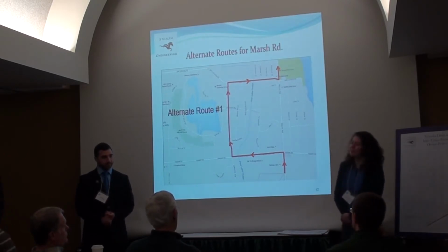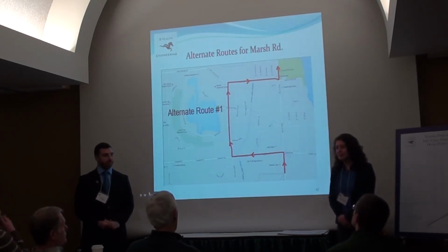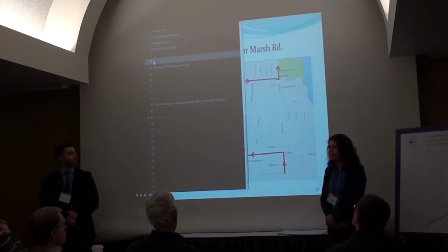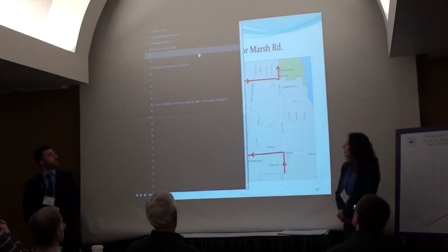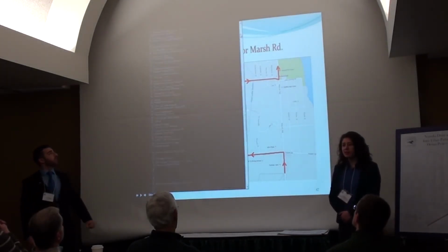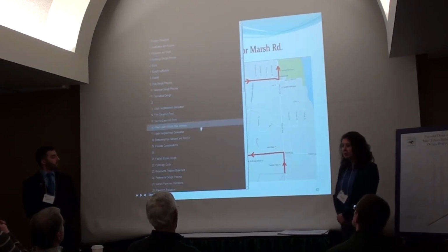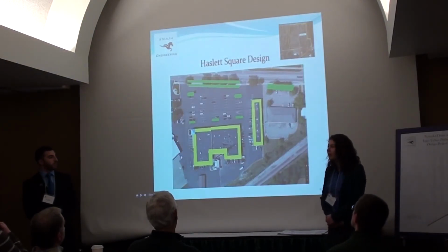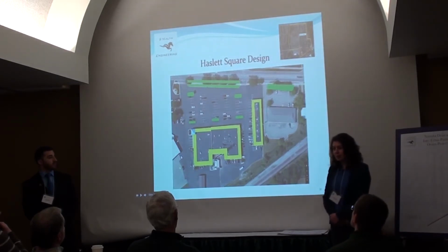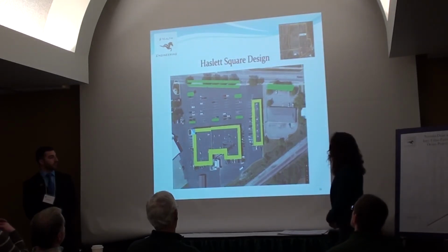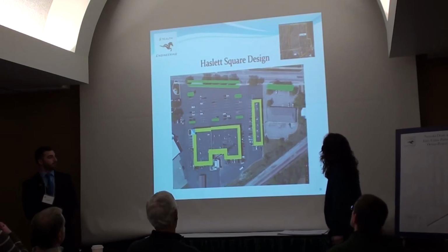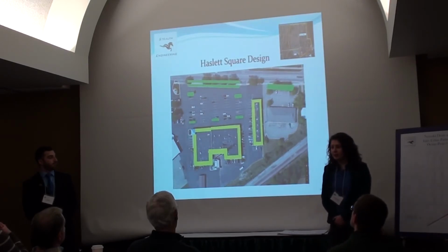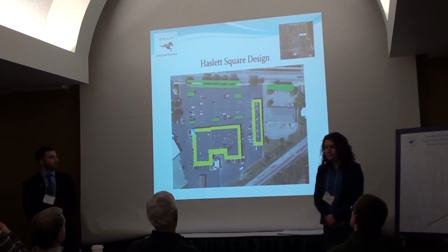Yep. I found the drainage area to be approximately 290,000 square feet. And there was a Southern Lake Michigan rain garden manual that I based my calculations off of, and I needed about 11,000 square feet of rain gardens. And I did meet that. I had 11,200 square feet.